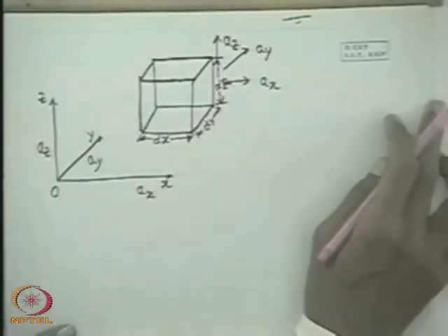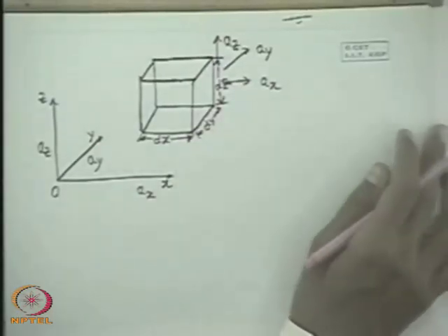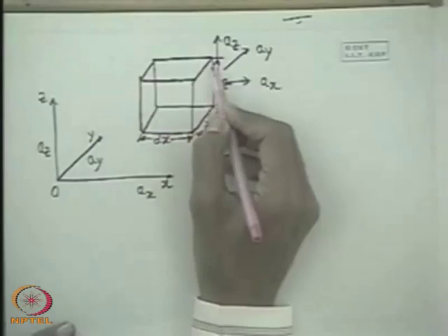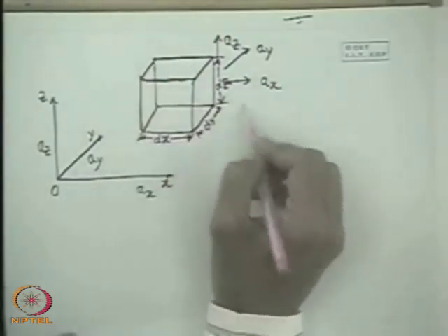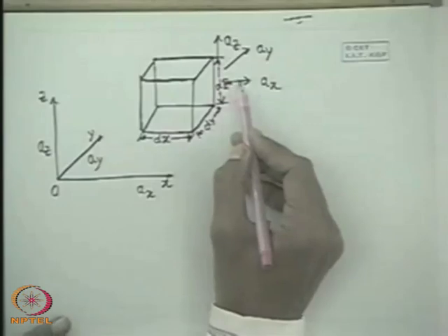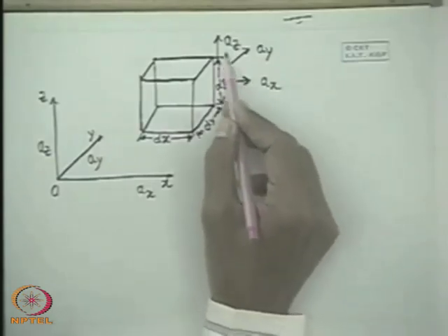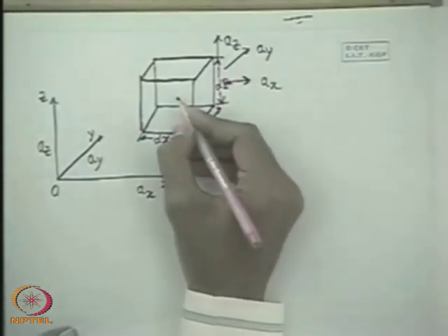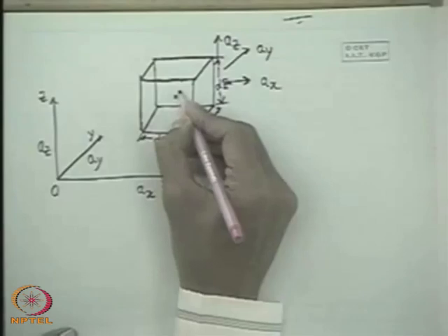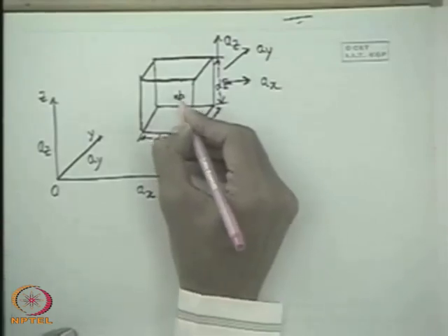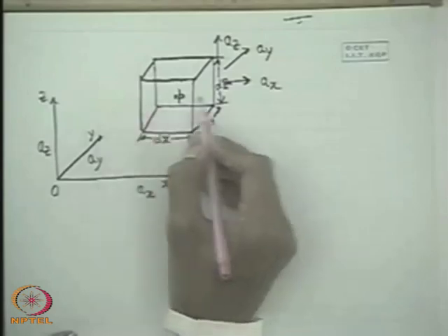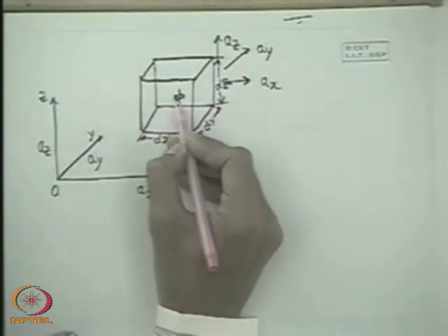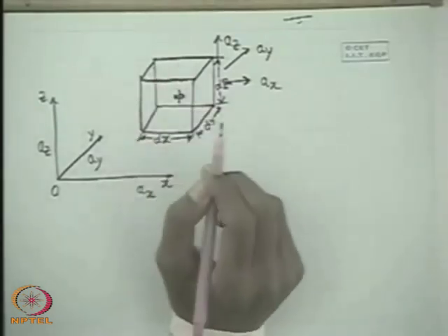Now, how do we find the pressure field? The simple thing is that the way we found the hydrostatic force equilibrium condition, it is the same way, only that an inertia force is acting because of the acceleration. It is extremely simple. It is better, and a more generalized approach, to define the pressure P at the center of this parallelepiped.